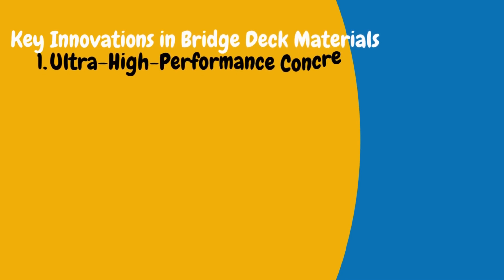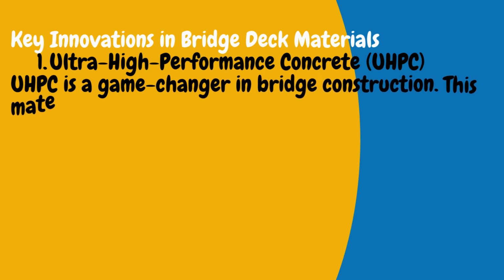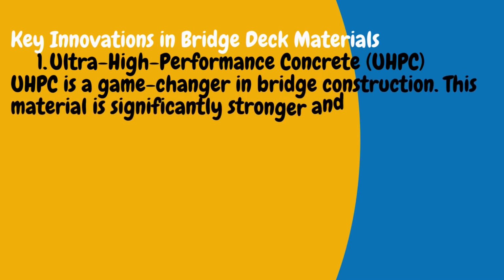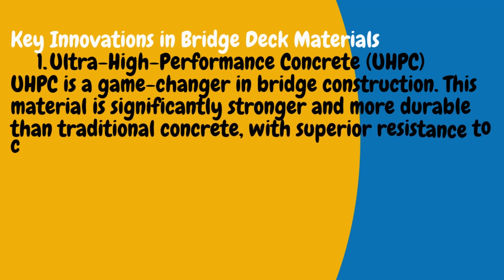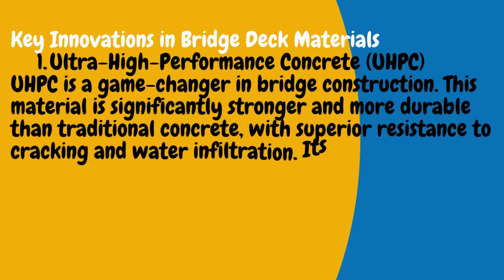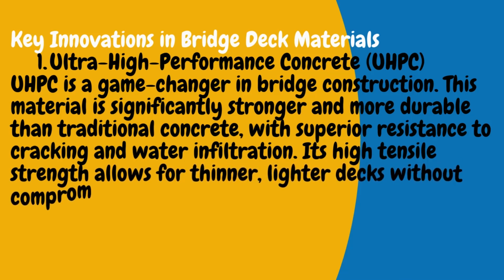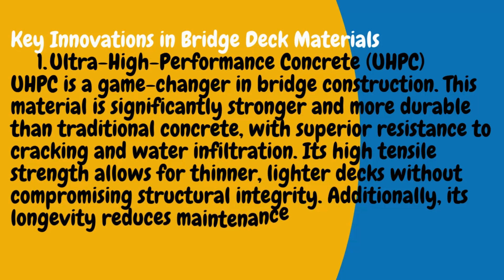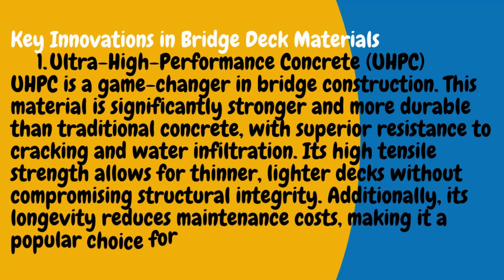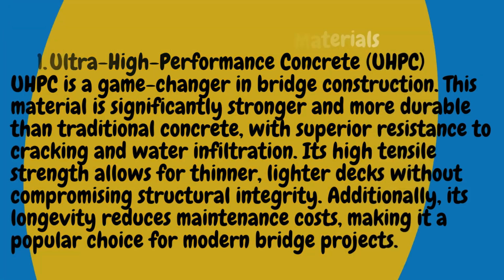1. Ultra-high-performance concrete, UHPC. UHPC is a game-changer in bridge construction. This material is significantly stronger and more durable than traditional concrete, with superior resistance to cracking and water infiltration. Its high tensile strength allows for thinner, lighter decks without compromising structural integrity. Additionally, its longevity reduces maintenance costs, making it a popular choice for modern bridge projects.